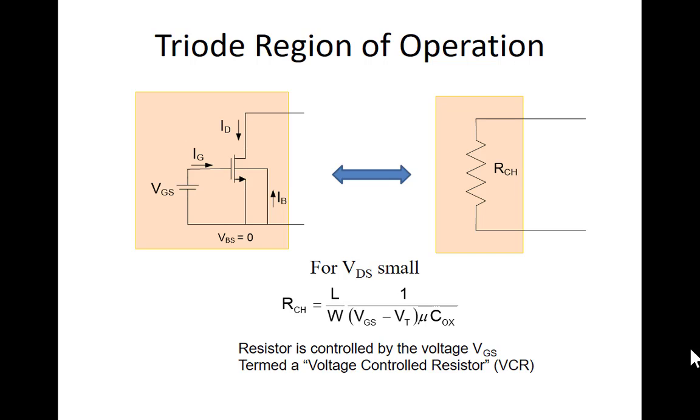This is an interesting resistor, because this is now a voltage-controlled resistor. As I change the gate to source voltage, I change the resistance. Is that a neat device? There are a lot of applications for it. It's the alternative to going in and turning a resistor or sliding a wiper on a resistor. We can control it with the voltage. You can control it with a computer pretty easily by having a digital to analog converter and letting that analog output control a resistance.